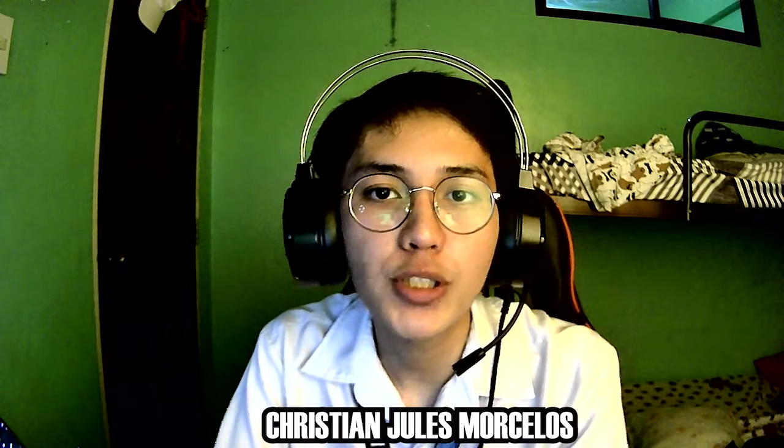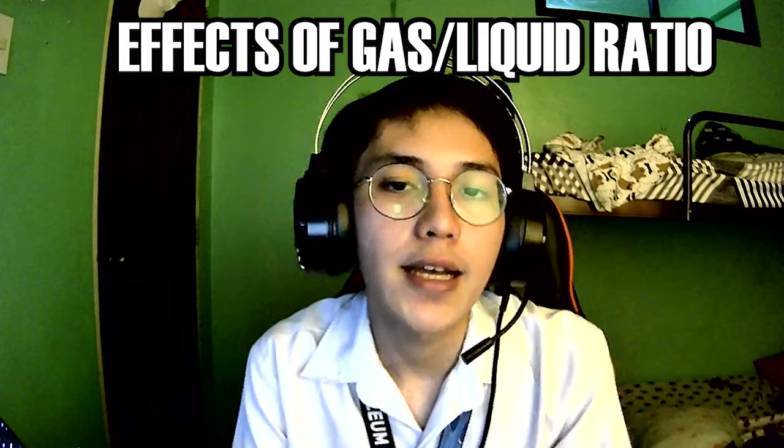I'm Christian Jules Marcelas and I'm here to discuss about the effects of gas and liquid ratio. The primary distinction between single-phase and two-phase reservoirs is that the producing GLR in the latter varies with time as reservoir pressure decreases. The density of the produced fluid decreases as GLR increases. This results in a temporary reduction in the required flowing bottom hole pressure. Figure 2.1 depicts the application of GLR curves.